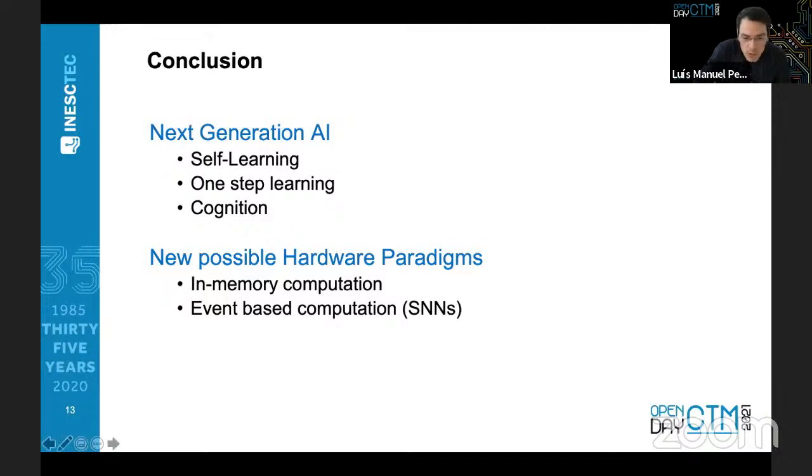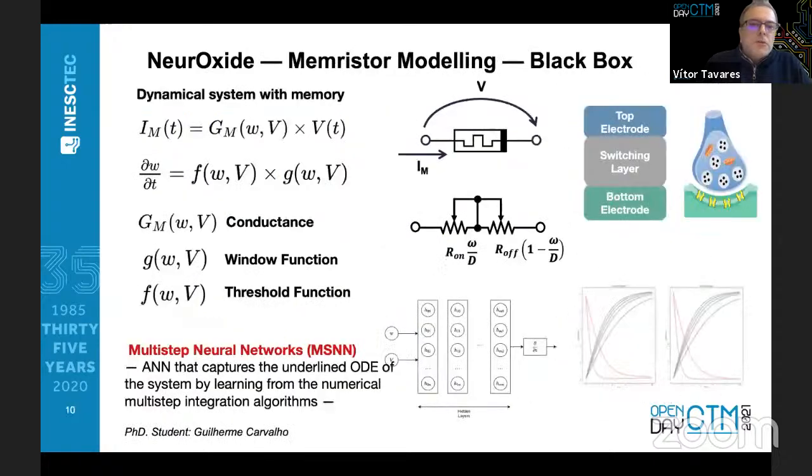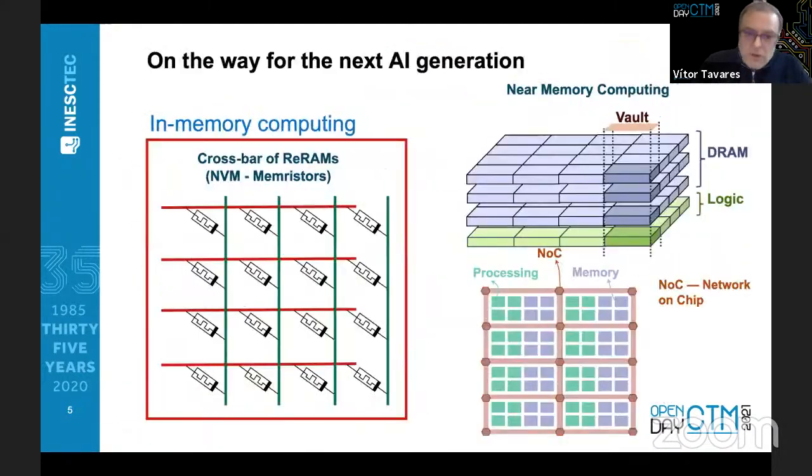So how much information can we store in these neuromorphic chips? First of all, let's start in principle, since the memory can be continuous, it's an analog device. So the first thing is, you have no resolution problems, okay? But you can think of this matrix, for example, for dot products. Let me show, like this one. This device can be very, very small, so nanoscale. So you can put millions of them in a chip.